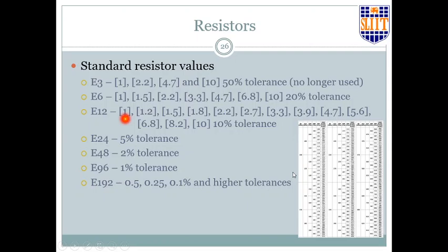Right? Now did I look at that? No. So next time you should be able to read the numbers, write the numbers without looking at the board. Because if you are given a bulk of resistors, which they will be giving in the lab, and asked to find a 10k resistor, you can't go through all these and find it.